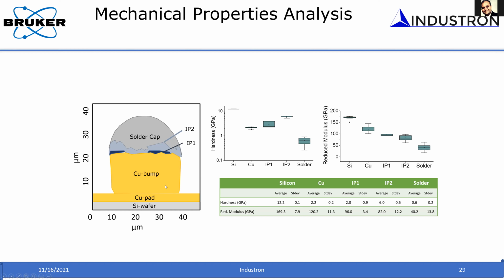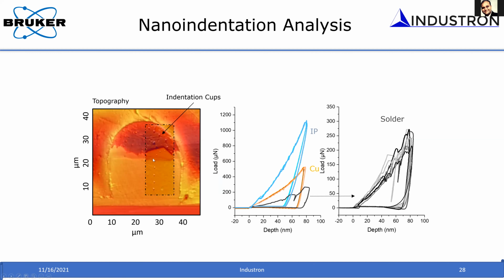And then you can see for different stacks of this material, in one setting, you can go and measure the properties across this whole length, and you can measure at different points for different materials how the property is changing as a function of position, right? You can do that for hardness as well. So with the SPM imaging, you are able to go and see where you want to do the indent, like how I am showing here, and you can also position it across the surface or across an interface, and you can measure those properties.